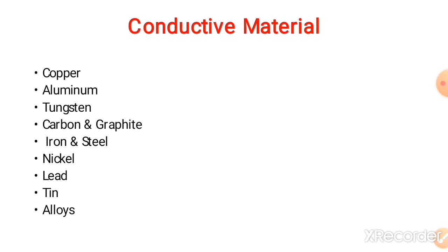The annealing process changes the physical and sometimes the chemical properties of a material to increase the ductility and reduce the hardness to make it more workable. The purity of copper is obtained with the help of electrolytic refining. The conductivity of copper is decreased when it is hard drawn into wire for use in machines. The annealing process is used before the material can be used in a machine.